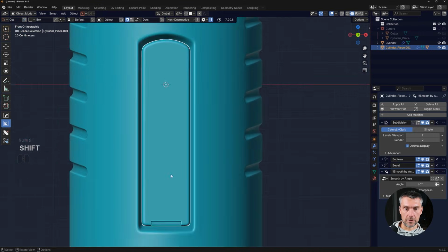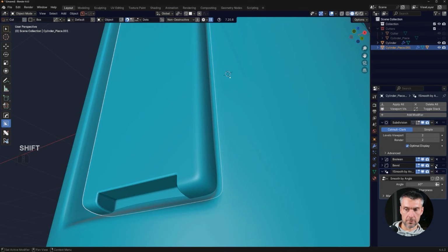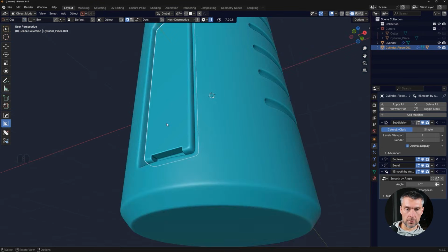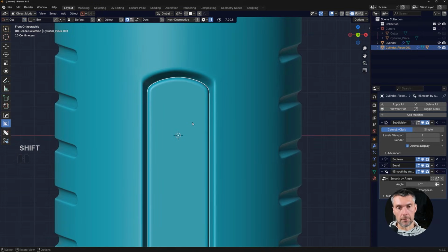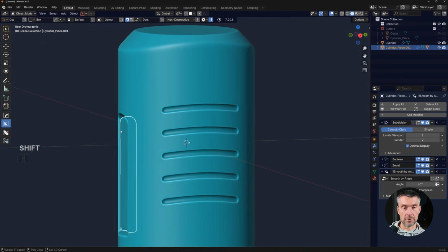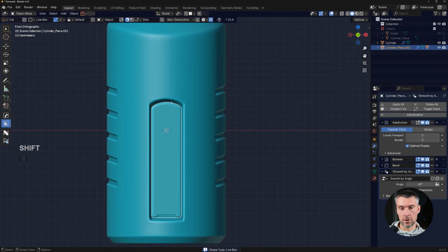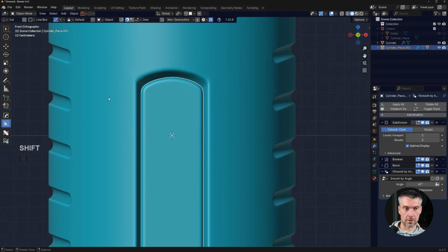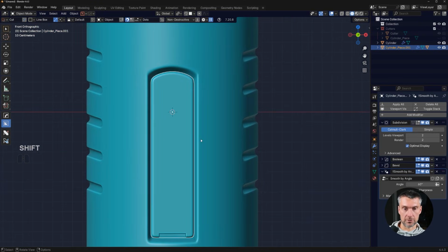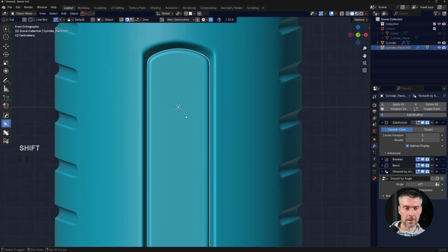So the good thing about running it the other way is that it's not destructive, because you can always remove the bevel if you want to and redo this whole shape if that's what you want, right? Booleans are fantastic for running mesh for rendering, or when you are concepting and you're not decided whether you want to progress with this design or not. That's a perfect time to run cuts like that. And once you decide what you want to do and finish with your designing, then you apply everything and you fix the subdivision, you know what I mean? So many ways of doing this.